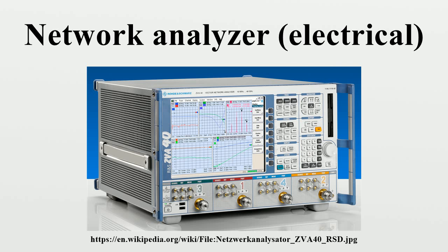Here the reflection and transmission data is formatted to enable the information to be interpreted as easily as possible. Most RF network analyzers incorporate features including linear and logarithmic sweeps, linear and log formats, polar plots, Smith charts, etc. Trace markers, limit lines and also pass-fail criteria may also be added in many instances.